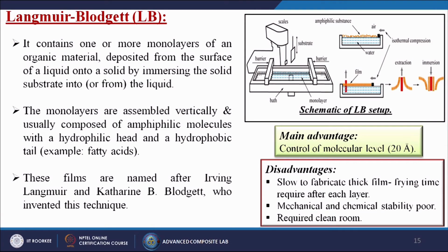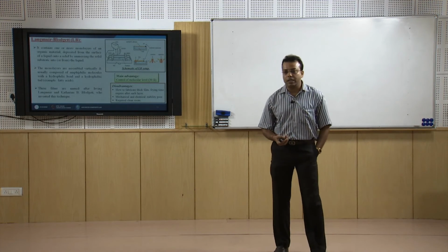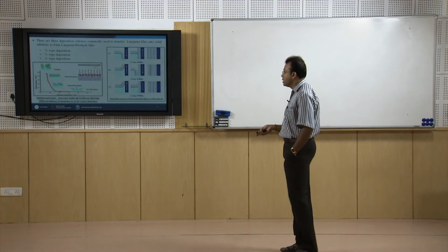Main advantage: control of molecular level around 20 angstrom. Disadvantages: slow to fabricate, thick film, drying time required after each layer, mechanical and chemical stability is very poor, and it requires a clean room. So, these are all the disadvantages of this particular technique.